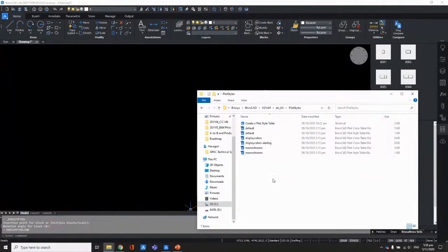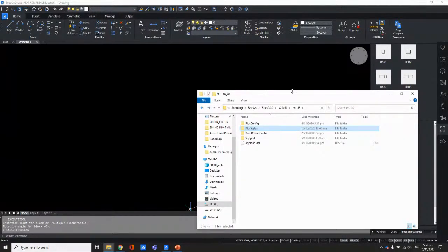The important thing is to know which folder you are placing them in. So just make sure that's the correct file path. And that's it, I think, for those printer files, your plotter, plot style files, that's all. And then once you've pasted them there, you'll find that they're already available for you. So I think that's all that we want to discuss on those things.